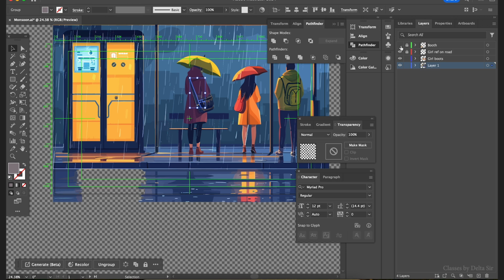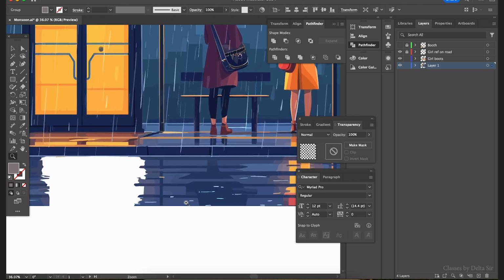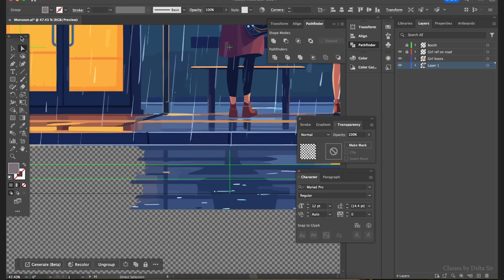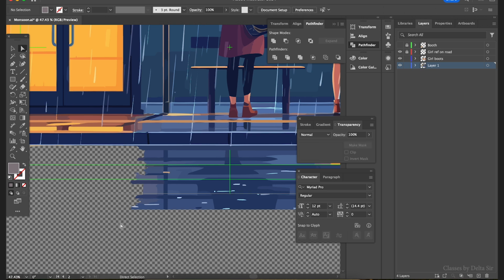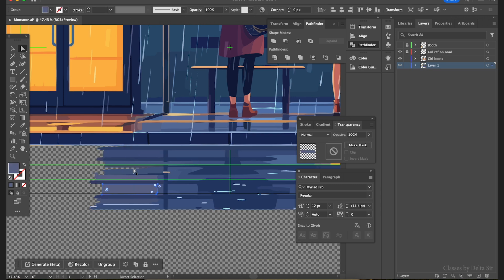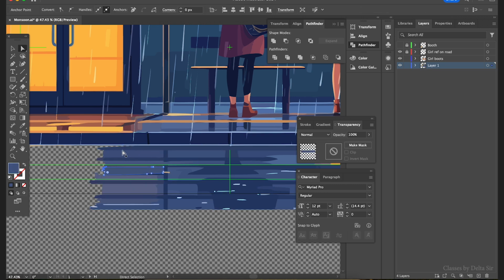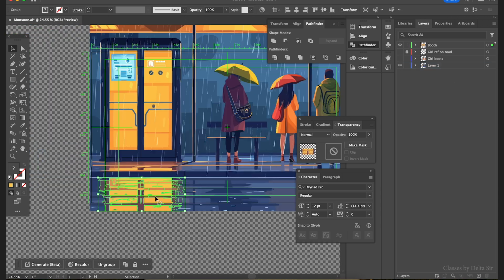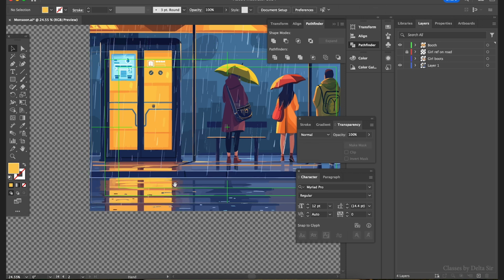This one and this. To give the wave animation in this part, we must have a filled area at the bottom. So there is a short technique. You need to select this tool, select all the vertices and just press Shift Left Arrow. So this area will be filled automatically. Enough few nodes are here. Yeah, this is fine. So if you move this, this will not show any blank spaces.